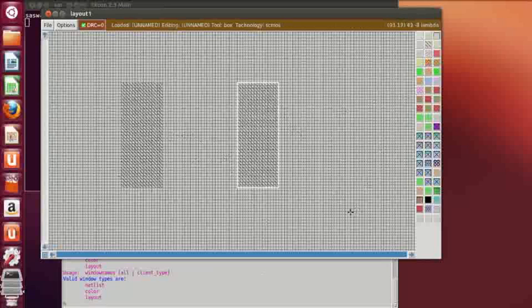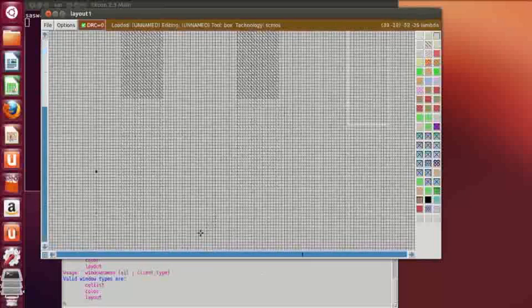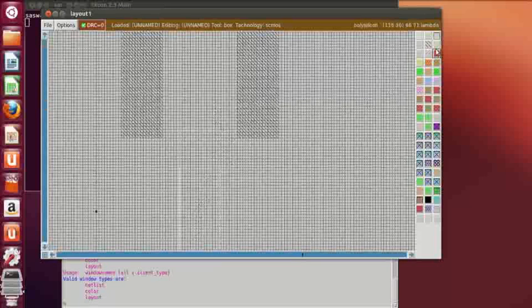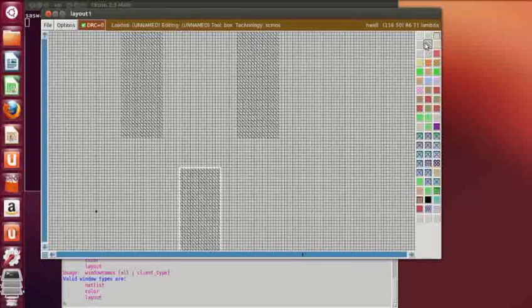So middle click on the anvil, and the third PMOS will be in series with these two PMOS. This is A, this is for B, this is A dot B, this part is A dot B plus C. So when there's a plus operator, or an OR operation, we'll use a series PMOS. So middle click on anvil.